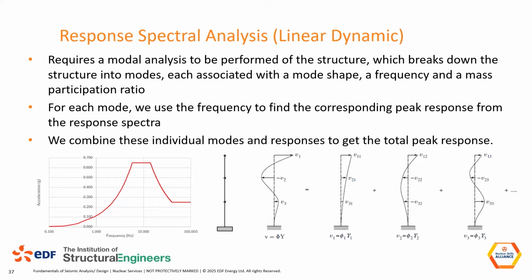Because we are splitting it up into individual modes and assessing each mode individually, this can only cover linear elastic analysis. We cannot be plastic because we do not find the combined response until the end. Each individual component is assessed as linear elastic, and the whole thing has to remain linear elastic for us to be able to combine them. So this is limited to linear elastic analysis, so we're not going into any plastic range.